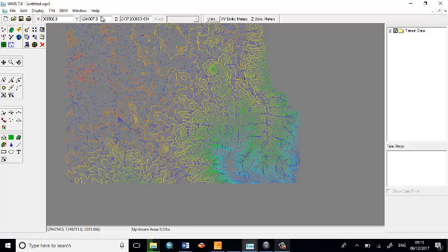This is X, Y, Z. These are the data values that you have collected from the site. So you can enter your easting, northing, and also what? Z values. But for the time being, I don't have any XYZ value. I'm just going to use the default values. So this outlet point should be on the river. Otherwise, it will not generate a watershed.